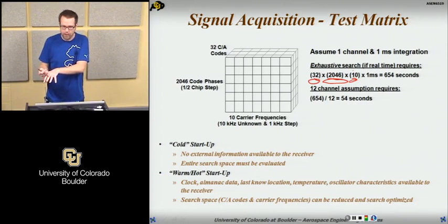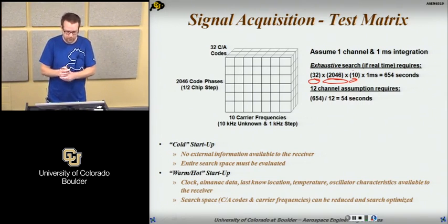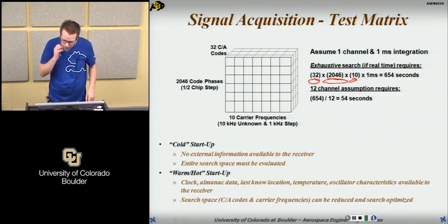If you look in the code, you have a parameter that says ACQ search band, that I think is set to 14. And that is actually plus minus 7 kilohertz. Does it make sense? Could it be plus minus 40? No, it's got to be plus minus 7, yes.